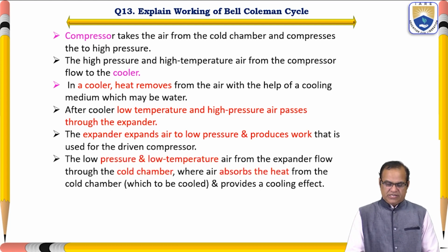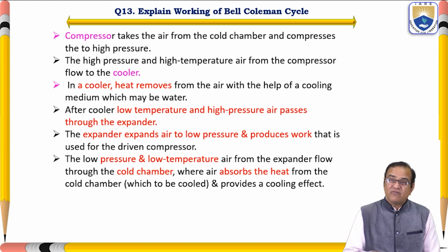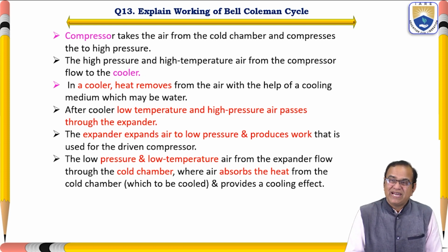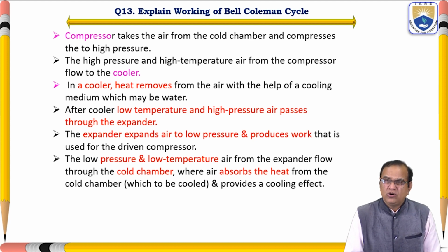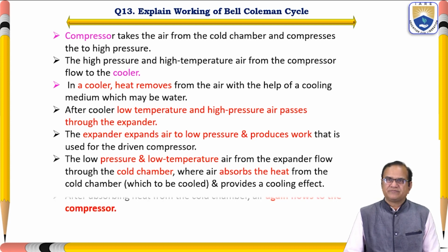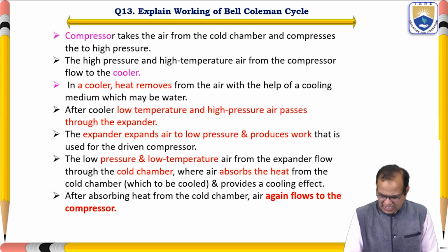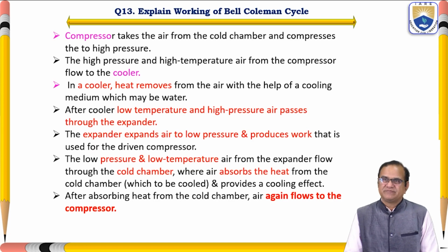The expander expands the air to low pressure and produces work that is used for driving the compressor. The low pressure and low temperature air from the expander flows through the cold chamber, where we want the cooling action to take place. The air absorbs heat from the cold chamber, which is to be cooled, providing the cooling effect. After absorbing heat, the air again flows to the compressor, and in this way the cycle is completed.